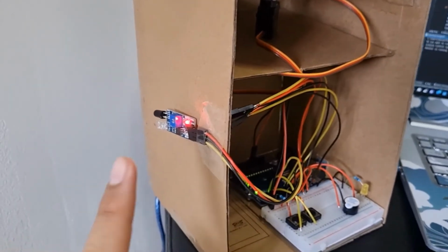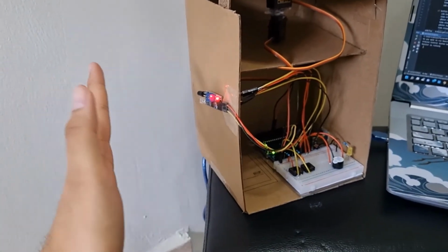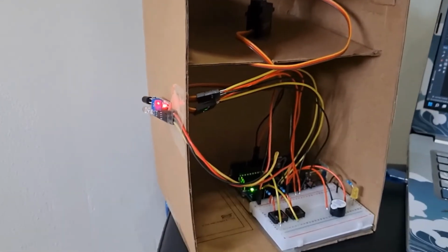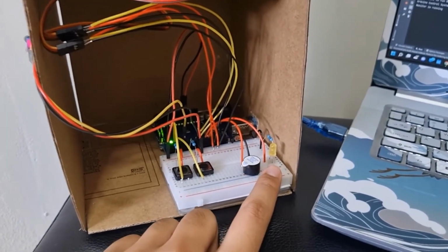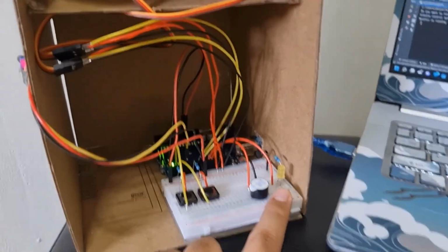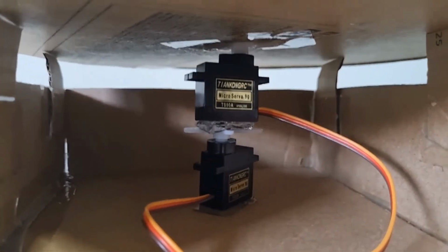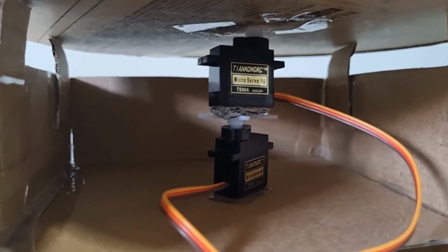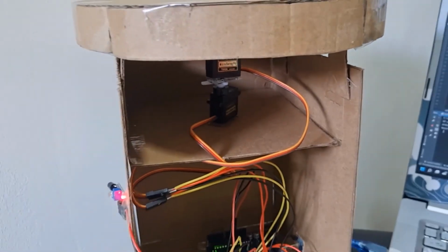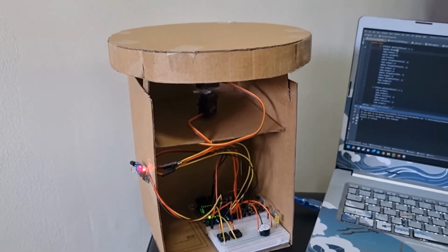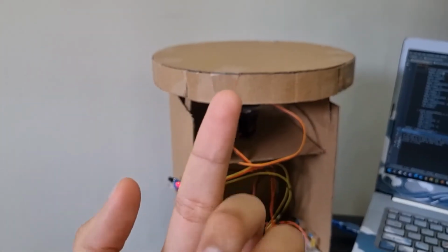There's an IR sensor here. So when the customer approaches and the IR sensor is triggered, the buzzer will beep for 0.1 seconds and then the LED will turn on. As the LED is on, the 2 servo motors will move through a 180 degree angle, which will make one revolution of 360 degrees, and once it has made 360 degrees, it will go back to its original position.